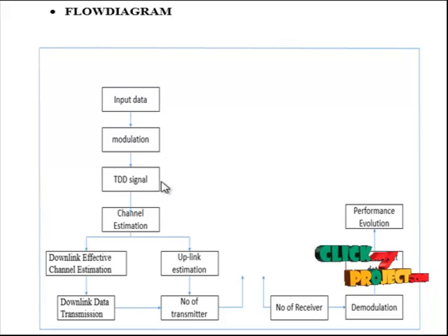Next, in the TDD signal, MIMO TDD, the input data goes through an encoding operation, and the encoded data goes through interleaving processes and binary to decimal conversion. Then QAM modulation is applied, and the modulated data has the cyclic extension added to generate the TDD signal. Multiple input, multiple output wireless technology in combination with time division multiplexing is an attractive air interface solution